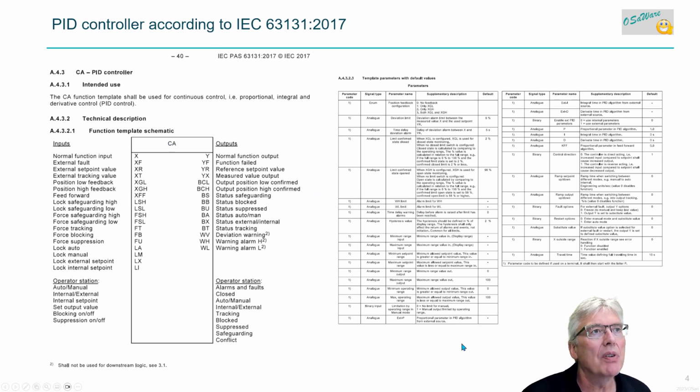And there's a lot of parameters that you can manipulate. Somewhere here you should have the PID, the KP, TI, and TD parameters too. And here are some initial values that you should have. So it's configured as a pure P controller, it looks like here, as a starter. But there's more to it. If you want to program a controller yourself that does something, maybe you should look into the norm, because this one tells you basically more about this. This is just a snippet of a little information.